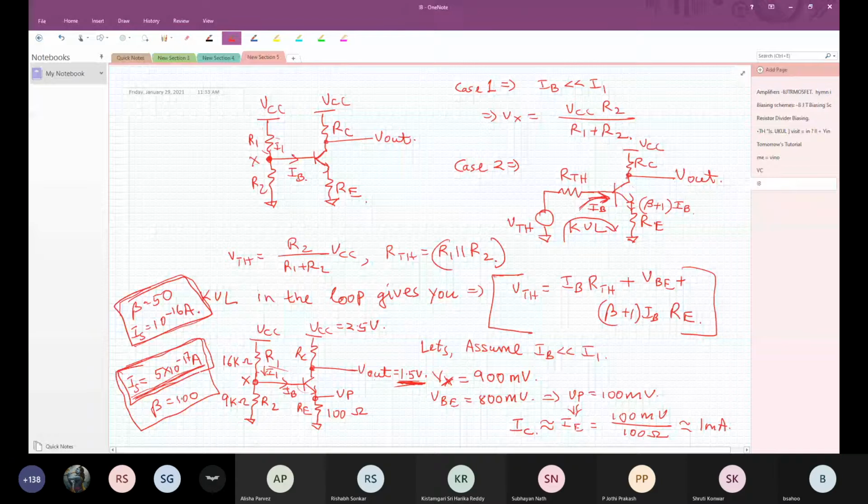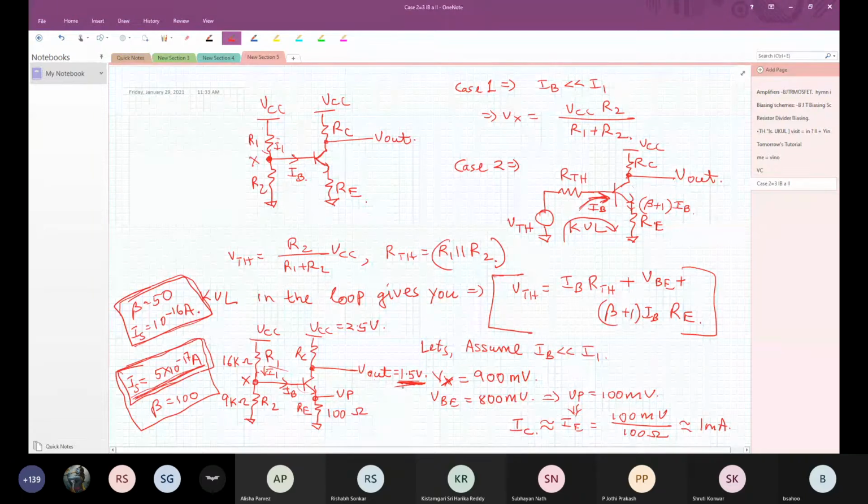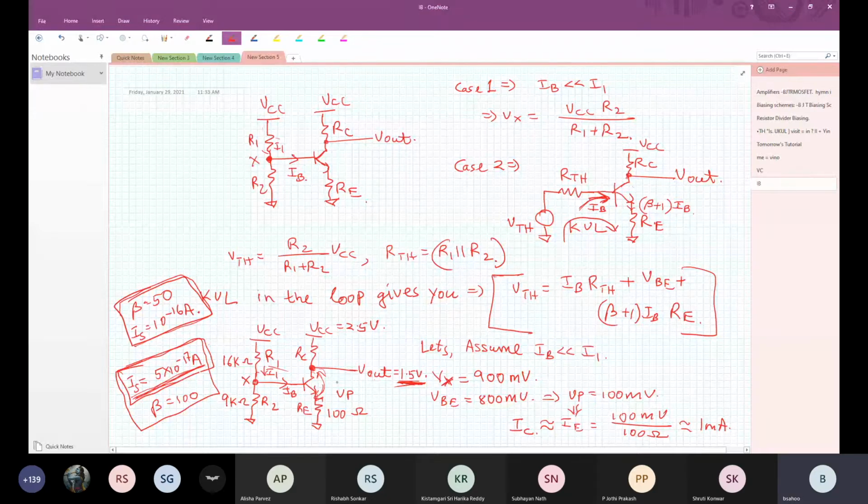Actually, when the new IS is 2 times 10 to the power minus 17, which you have given previously, then the change is almost 0.4 volt in VC. VC changes almost 0.4 volt. VCE or VC collector? VCE is this difference. Yes, VCE changes by 0.4 volt, and the collector changes by about 0.6.